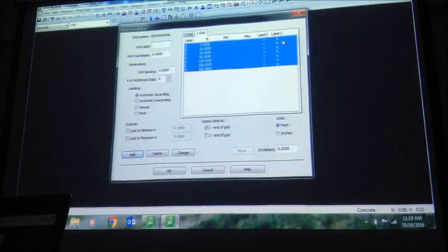If you know, say for example, this is a beam element, right? The way we define in any structural is that we call the first one, the left hand side is I, the right hand side is J. Ith end, Jth end, right? So here it says that your label, grid level, like say this one is 2, should be written as 2 here on the ith end, on the left side.